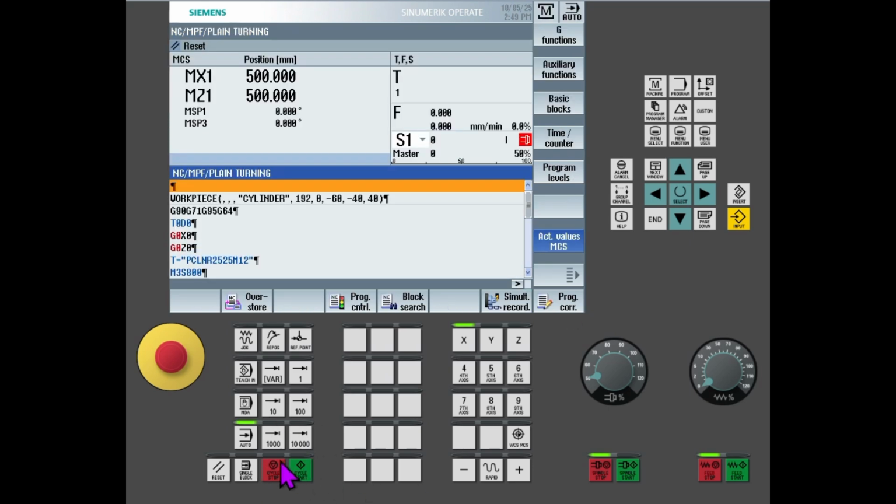If you want to execute this operation, then press execute. Then the program automatically comes to the machine interface, and automatically the auto mode gets activated. Now press cycle start if your offsets are okay. If your tooling has been done, and your chuck clamping of the workpiece is done, then you press cycle start, and you will see the machining process.